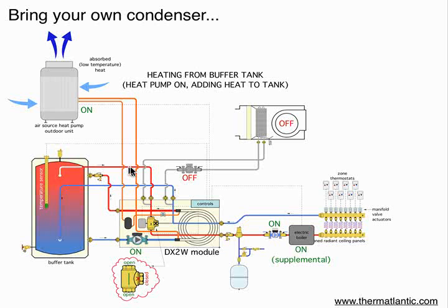If a temperature boost is necessary, the electric boiler can do that. It goes off to the low temperature distribution. In this case, I'm showing radiant ceiling panels. Could be floor panels, wall panels. And then it comes back and goes back to the buffer tank. So the buffer tank allows you to have a highly zoned distribution system and not short cycle that refrigeration system.